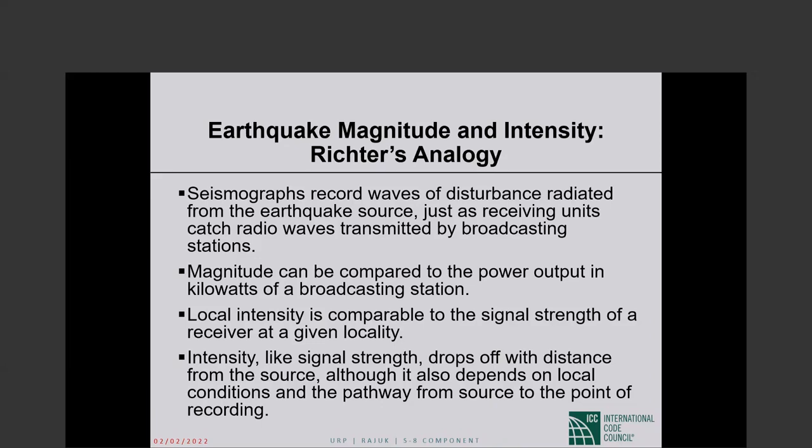How quickly did it take place? Is it a shallow focus earthquake? Is it a deep focus earthquake? All of those source related factors will determine what your structure feels at your site. But it is also the source to site transmission path. Are the seismic waves coming through mountain ranges or are they coming through alluvia, on riverbeds?